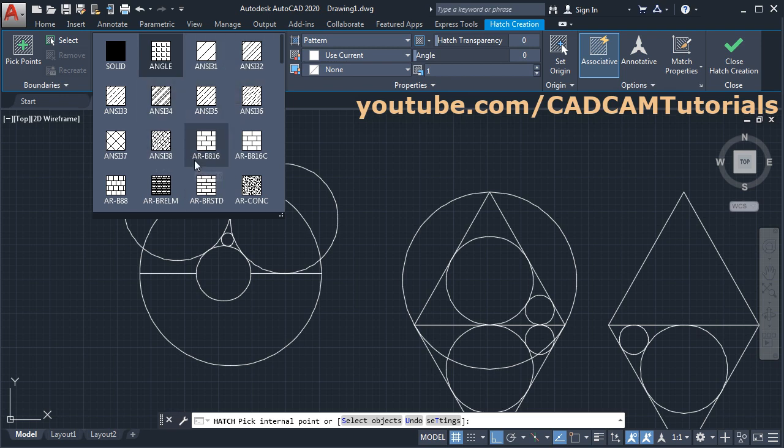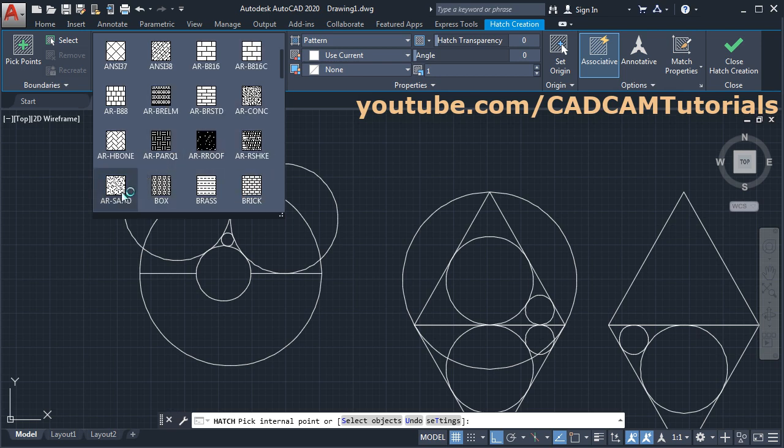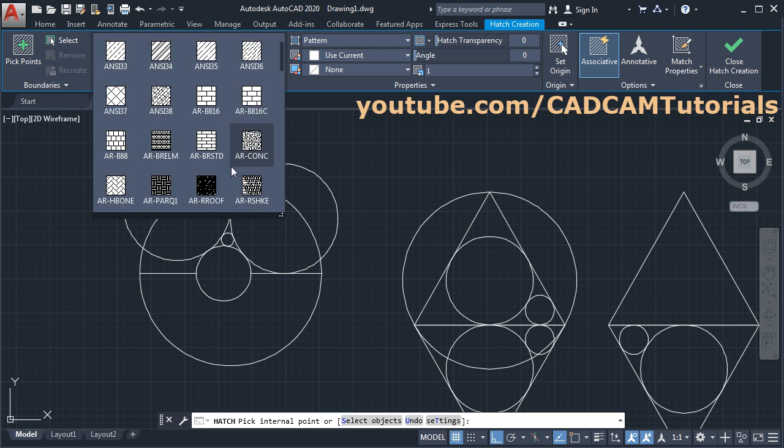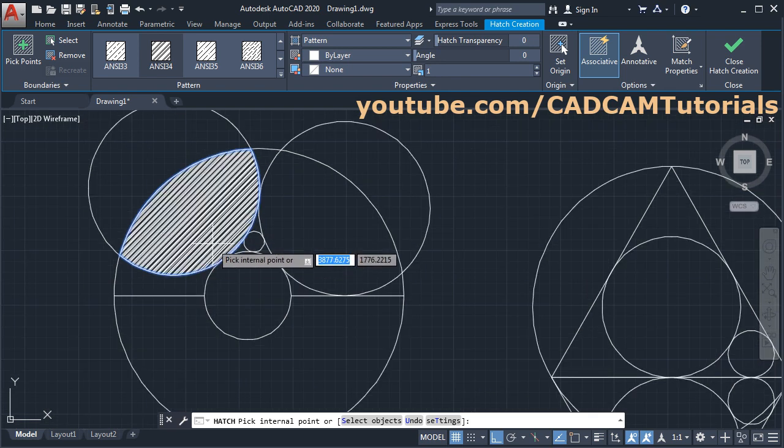Hatch patterns starting with AR are the architectural hatch patterns. In architectural, there are brick patterns, then concrete, then sand. If you scroll down, different patterns have been given. Then there is gravel. So at first I will choose this NC34. Then take your cursor inside the object where you want to place the hatch. Click there. Now it has created this hatch pattern.